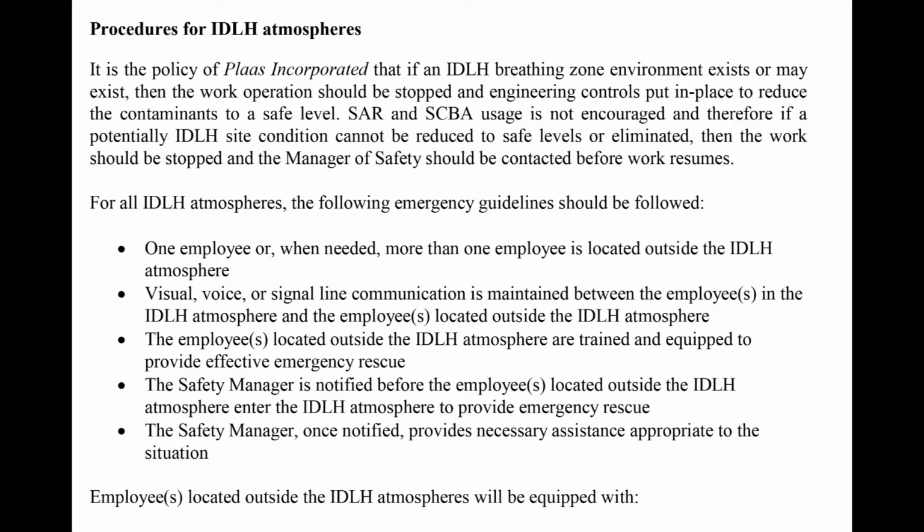Procedures for IDLH atmospheres. It is a policy of Plaas Incorporated that if an IDLH breathing zone environment exists or may exist, then the work operation should be stopped and engineering controls put in place to reduce the contaminants to a safe level. SAR and scuba usage is not encouraged, and therefore, if a potentially IDLH site condition cannot be reduced to safe levels or eliminated, then the work should be stopped and the manager of safety should be contacted before work resumes.